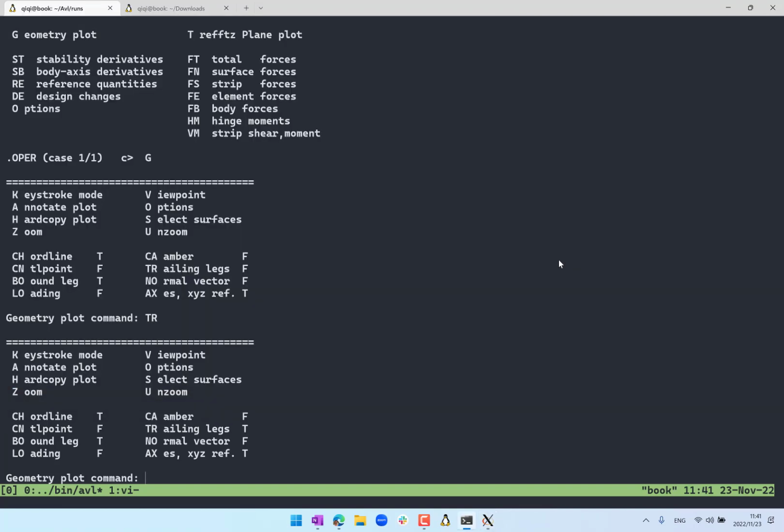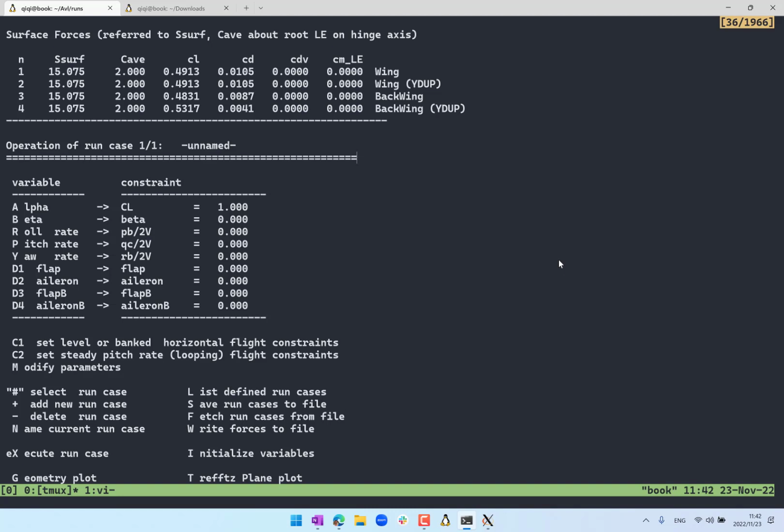Oh, one thing I forgot to mention. If you look at the forces, the two sides of the wings on the airplane behind have different CL, right? What does that mean for the airplane flying behind? It's going to roll away from the front airplane, because the wing closer to it has a higher lift. So one thing you can do is change the ailerons. In practice, you would deflect the ailerons to counter the roll moment, and that's something you can do.